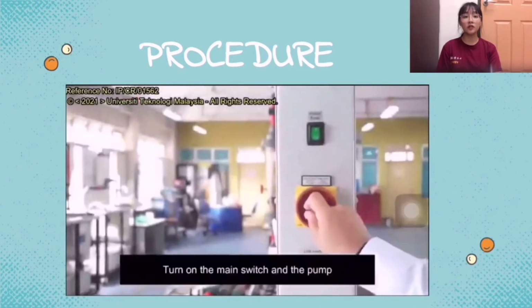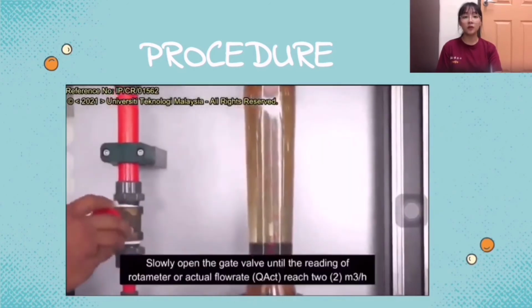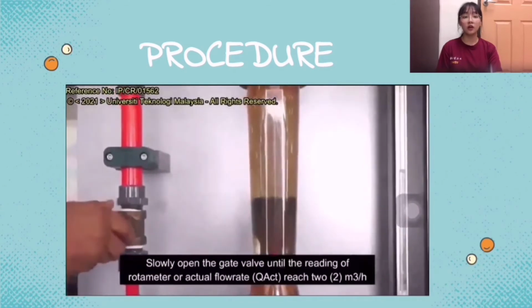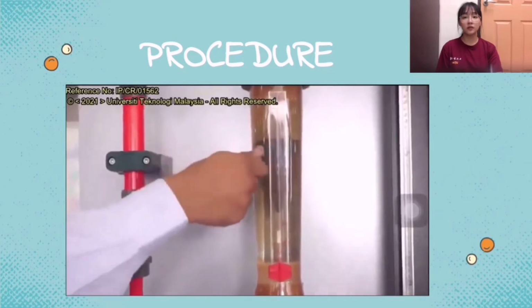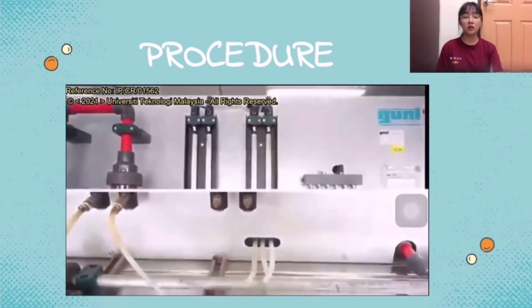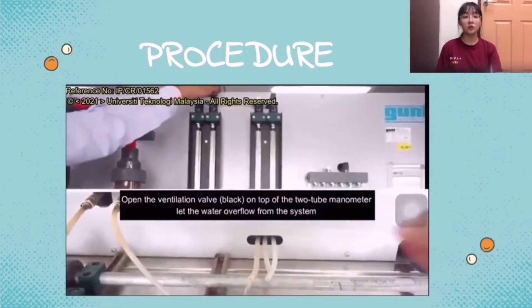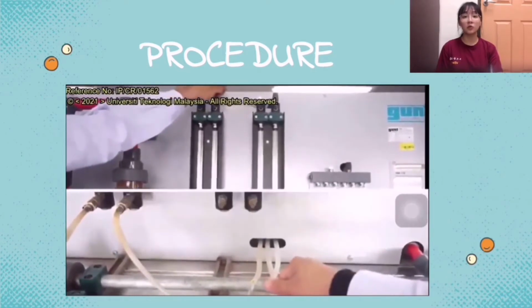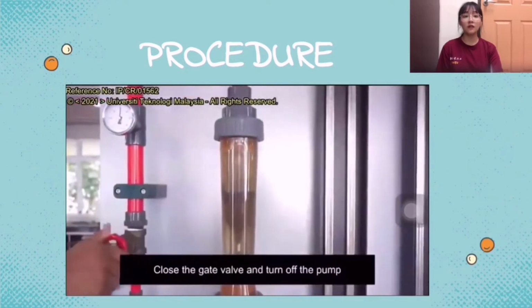Turn on the main switch and the pump. Slowly open the gate valve until the reading of the rotameter reaches 2 m³ per hour. Open the ventilation valve, black color, on top of the 2 tube manometer and let the water overflow from the system. Close the gate valve and the pump.